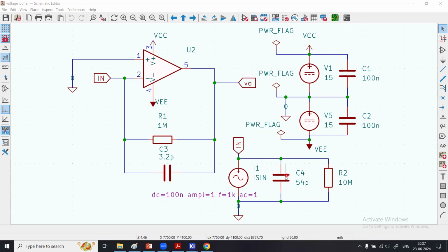So this capacitance, one end is connected to the negative pin of the amplifier with respect to ground. So this is the input capacitance of the photodiode plus the differential capacitance of the amplifier, because the positive pin of the amplifier is grounded. So this capacitance is connected between these two pins. And part of this capacitance is some other parasitic. So you see, this is the total capacitance.